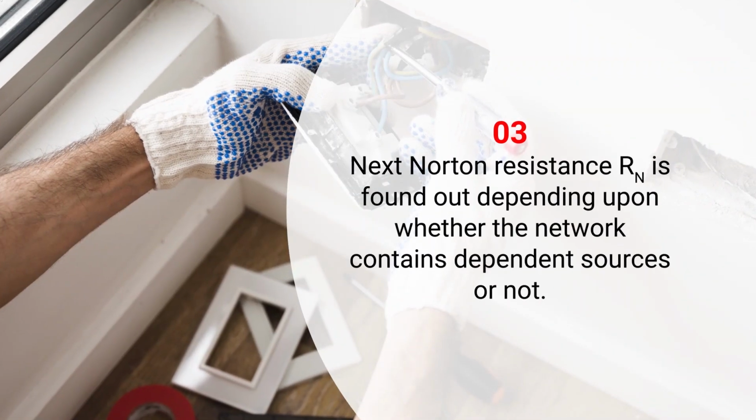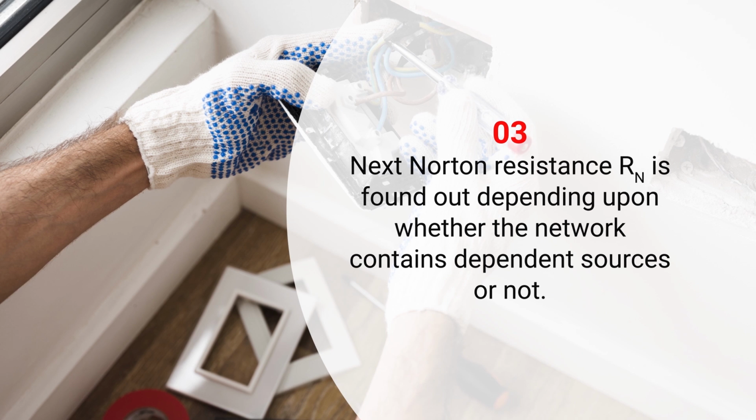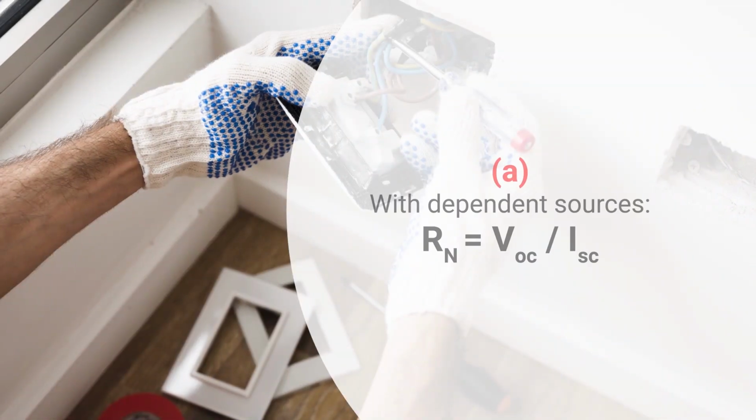And the next step, the third step, is what? You have to find the Norton resistance. To calculate the Norton resistance, the method is the same as you calculate the Thevenin resistance. So Norton resistance is the equivalent resistance looking from the two terminals into the network while all independent energy sources are replaced by their internal resistance. So there may be two cases when you have to find the Norton resistance. The first case is when there are dependent sources.